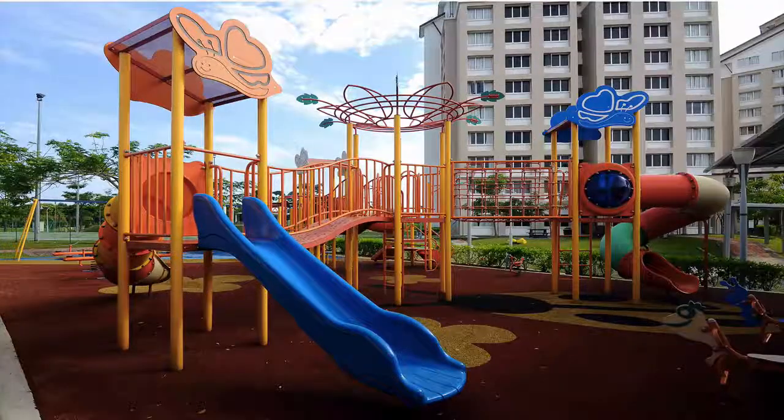Some other conditions. Equipment accessible to children must be sturdy, stable, and free of hazards, which includes sharp edges, lead-based paint, loose nails, splinters, protrusions, pinches, and crush points. Any corners or edges should be rounded or should have capping. Plugging or covering open ends of tubing will also keep out curious fingers as well.